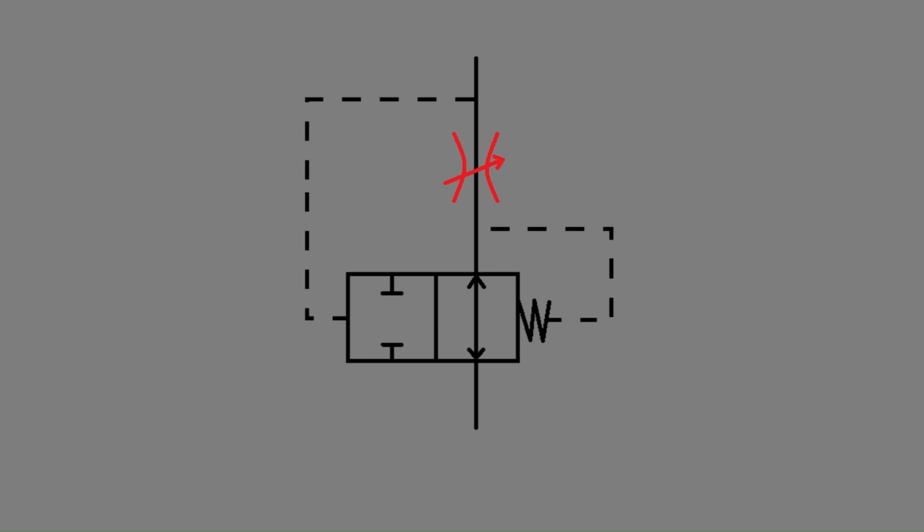It is important to remember the pressure drop we talked about here is the pressure drop across the orifice, not the whole flow control valve. In reality, the pressure drop across the whole valve can be much higher than that of the orifice, depending on the pressure requirement of this function and the other functions in your system.